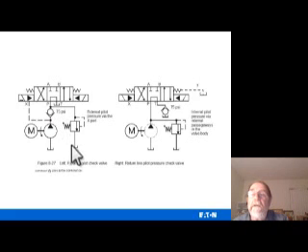Okay, these are all going to the same location. You draw them in these circuit diagrams to make it easy. It's like the ground in an electrical circuit. And then these ports are blocked on A and B. Once you get some pilot fluid here, it's going to move it to the right and crisscross this, and whatever A and B are connected to is either going to move that actuator in or out or turn that motor in one direction or the other if it's a hydraulic motor. And then this is another way of doing it here too.